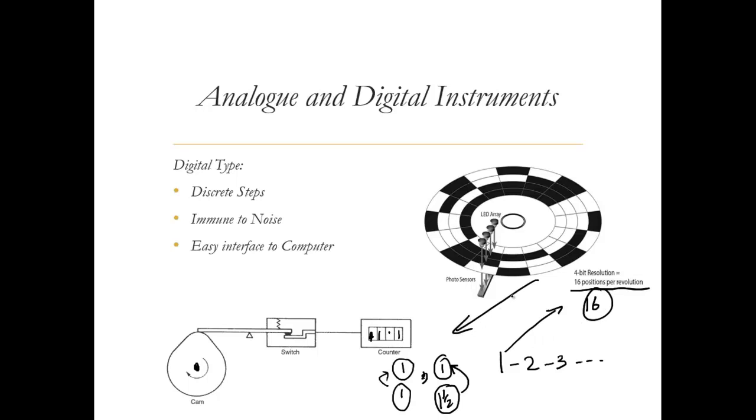But sometimes in the control of robotics, or in other complicated applications, CNC machines and other things, whenever we want position sensing or velocity sensing, the higher the resolution, the better the control is. So this 16 is obviously better, and this encoder is better than the previous one, but it still has 16 positions per revolution, which means we can measure up to 1/16 as a resolution. If we want a resolution better than this, we need something with 1000 CPR, which is counts per revolution.